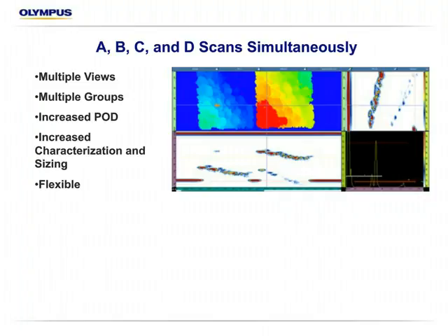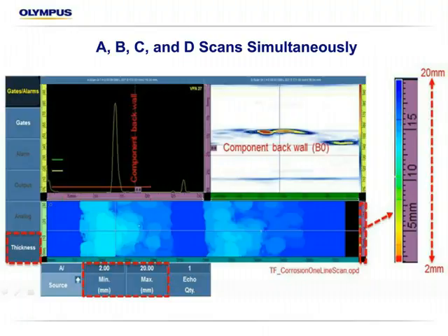So this is typically what we're looking at. We have the C-scan as our map, so we've either done a one-line scan in a straight line, or we maybe did an XY scan over a larger area. And we've defined the unit based on what type of thicknesses we are concerned with, nominal wall to some other level, and this palette is fully customizable to the application. So in this case, it's set from 20 millimeter nominal wall. Everything in dark blue is going to be good wall. We're starting to see some light blue. We're into the 15 millimeter, 14 millimeter range, as we can see on the palette.